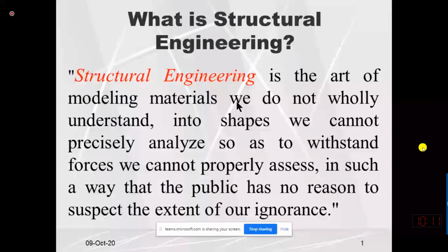And then if we know the maximum bending moment and maximum shear force in a beam, then we compute the maximum shear stresses or maximum flexure or bending stresses produced in the beam. So actually we use formulas to compute the shear stresses and bending stresses. The shear formula is tau equals VAY over IB, and the flexure formula is sigma equals MY over I. Actually, both formulas are theoretical formulas.